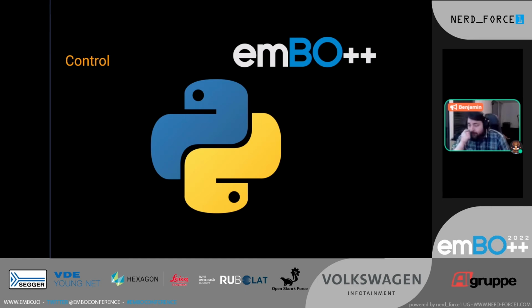So we need to orchestrate all of this because we now have multiple components in play. We need to control the J-Link, we need to control the dev board, and for this I'm using just a few Python scripts that talk with PySerial to the Bluepill board, send it serial commands, and on the other side it talks with the PyLink library to the J-Link to just try to debug the target.